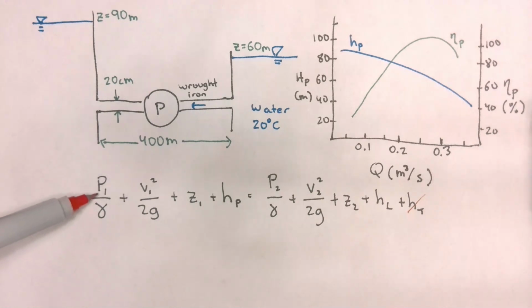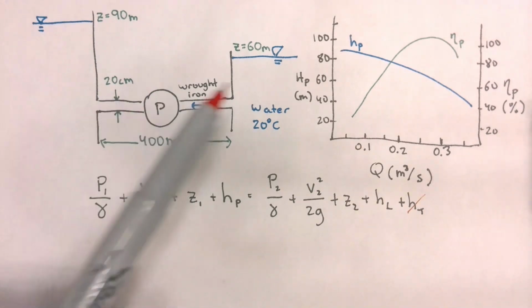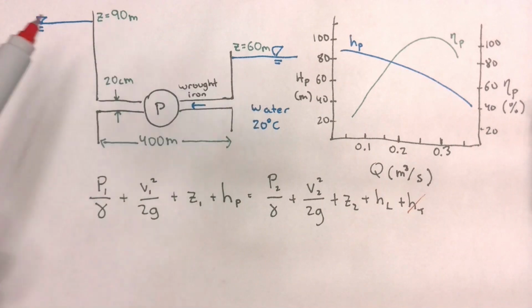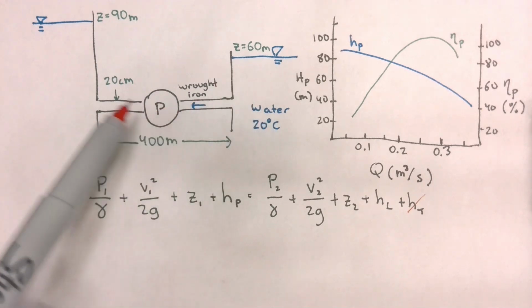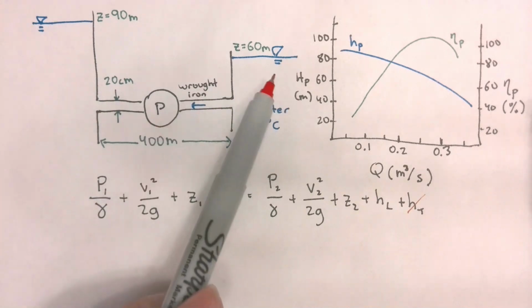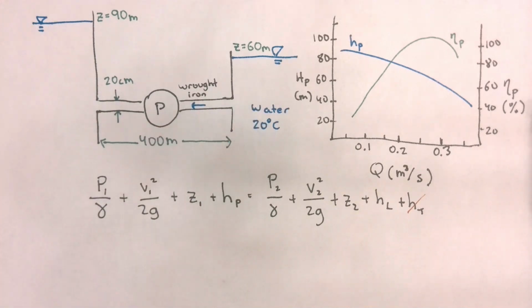What is the pressure at the top of the inlet control surface? First of all, which one will be the inlet? Would it be the left or the right? The right. Okay? Because flow will travel from this lower reservoir through the pump into this higher reservoir. So this would be our inlet. So what's the pressure there? It's just atmospheric. Good. What's the pressure at this point?